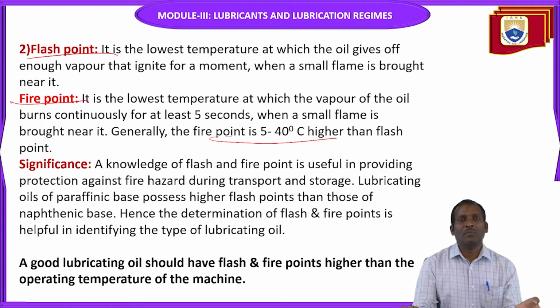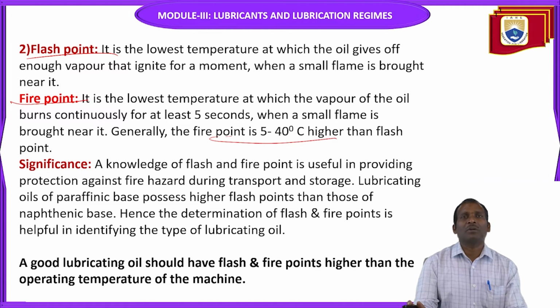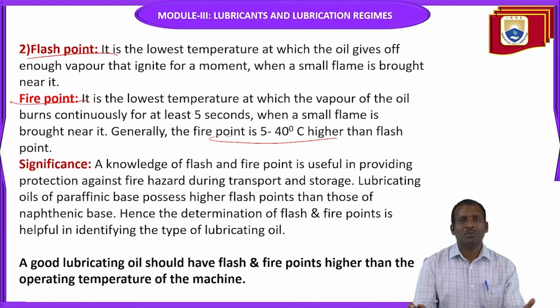Those types of oils, if used in a particular application without studying the properties of the lubricants, lead to major fire accidents. So to protect against these types of hazards, you should know about the flash and fire point.